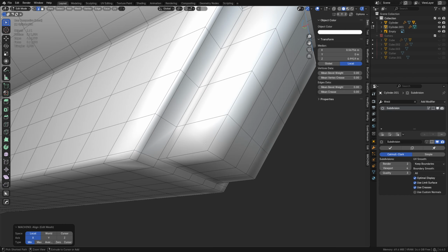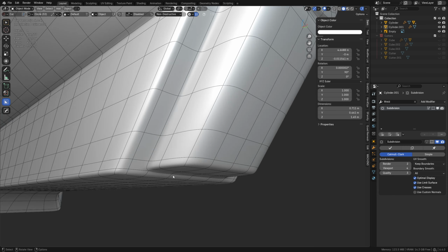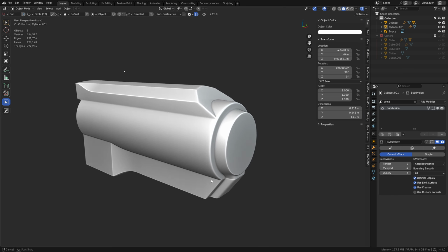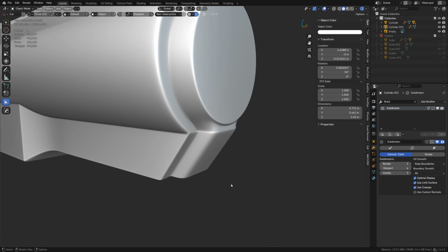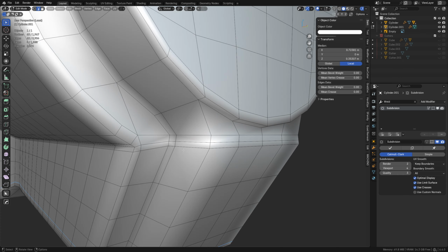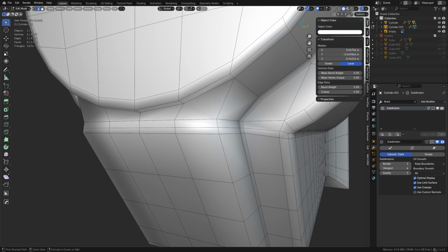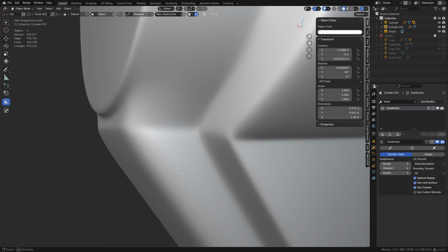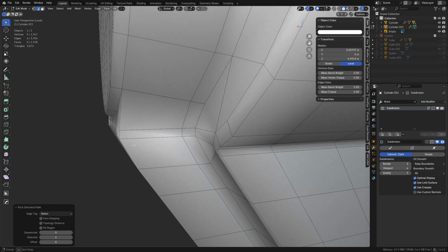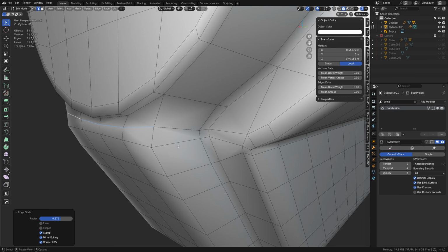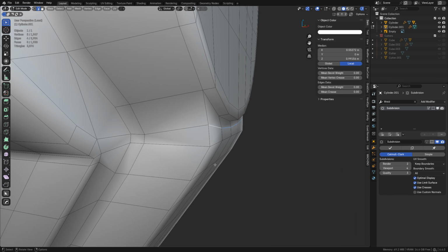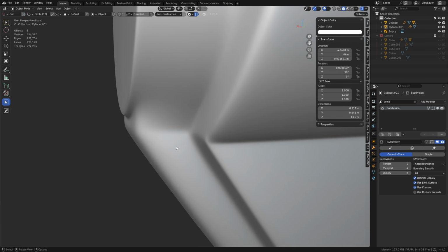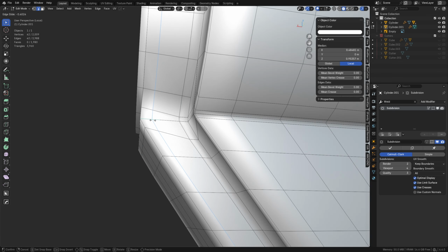This should mostly work, but check this out. We have a little edge we need here. All right. And there we go. So just this one little edge here that I'm not too happy about. So we're just going to slide it down. Softens it up. And this one we could probably slide up a little. Let it soften that top side. So if you want those sharper, you just keep them closer basically, right? Might be good to put another loop cut here too.